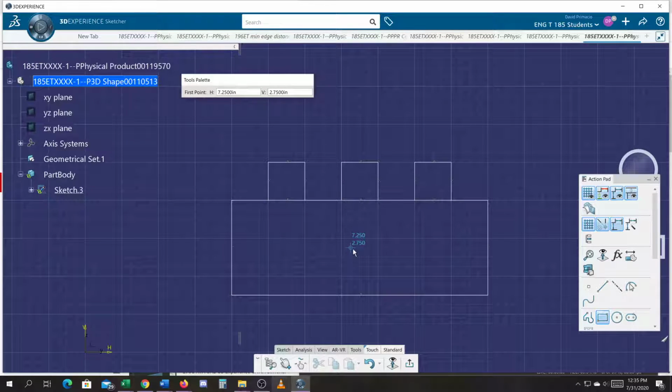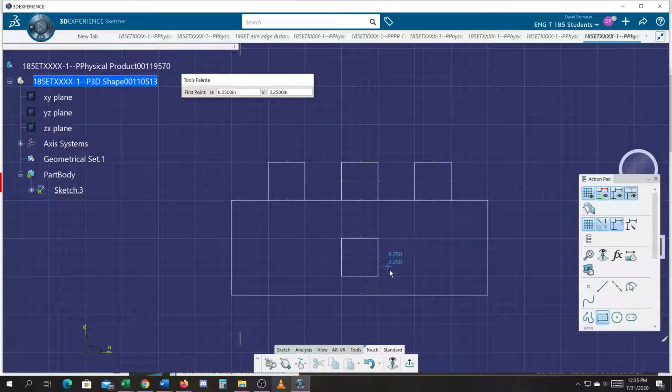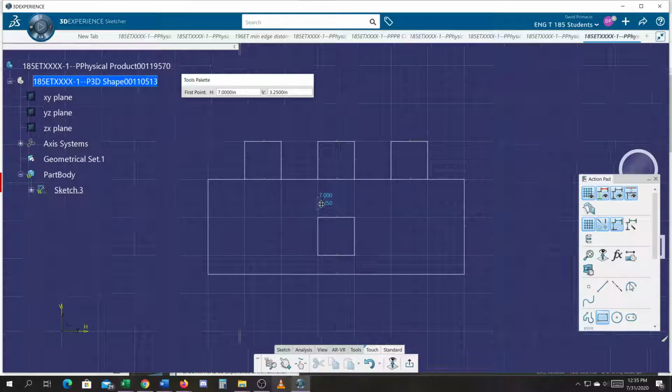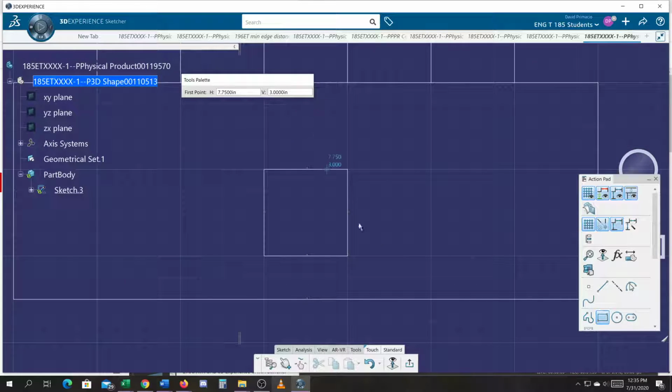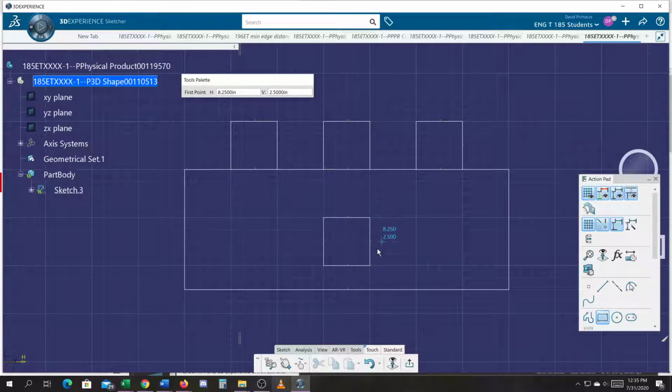And then I built a rectangle, because if I build this rectangle here and here, I'm either going to get a coincident like I did here. Unfortunately, I can't zoom because you probably won't see it much more. It keeps making the coincident smaller as you get closer to it. Anyways, I can see there's that coincident. I've linked that line up to this. If I don't want them to be the same size, you want to constrain them in such a manner that I can edit them later. So when I create that rectangle, even if it were dimensionally the same size, I wanted that flexibility to change it at will. So I'm going to make it undersized so it doesn't link up to that.